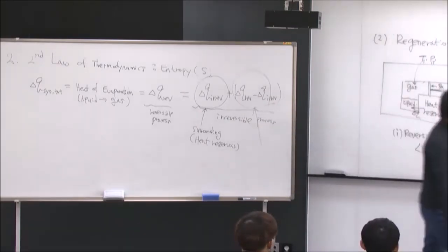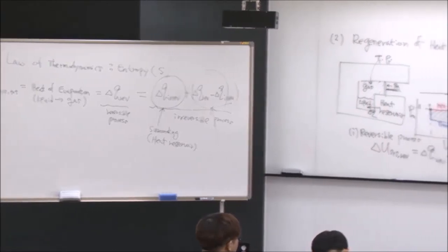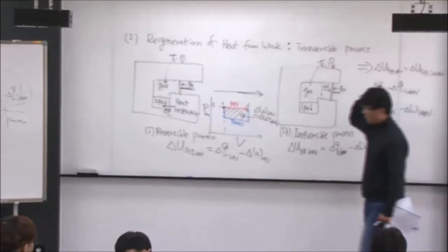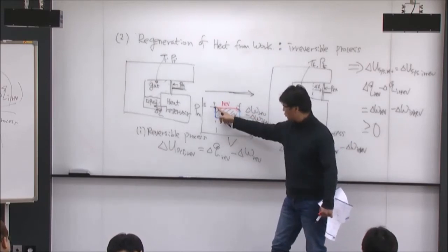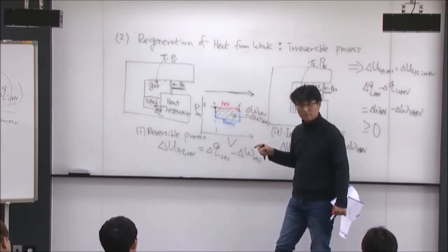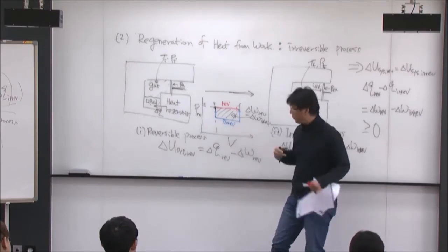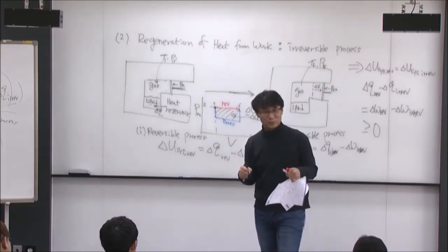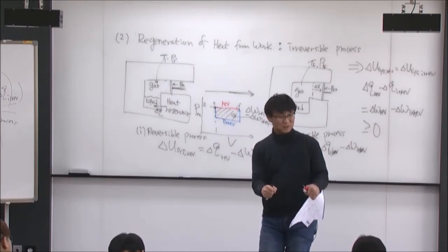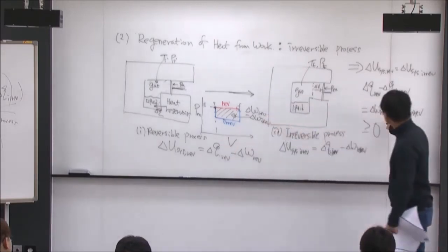If you look at it here, this minus this is the same as this minus this. Coincidentally, this is the same quantity. And if you think about your process here, potentially my system was supposed to do this amount of reversible work. However, my system only did part of that. I have 100% potential to do the work, but because of the irreversible process, I'm using only 80% of that capacity to work. Then the other 20%, where is it going? That actually coincidentally matches this one.